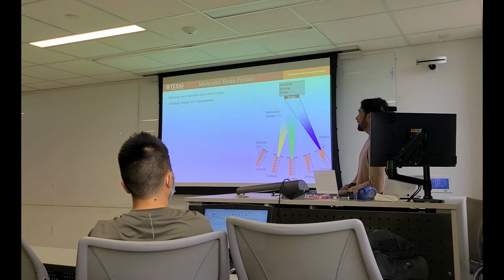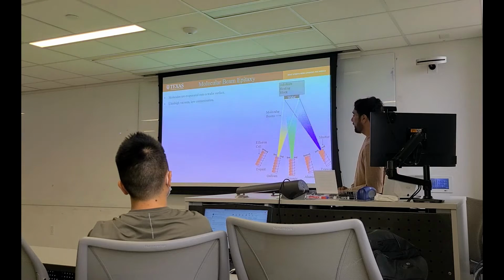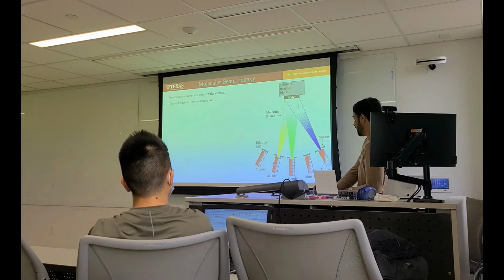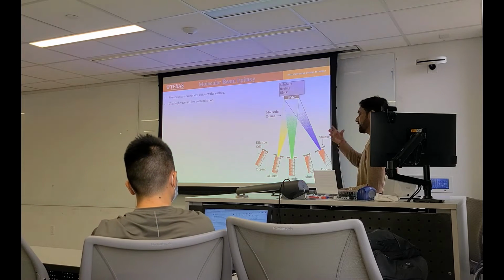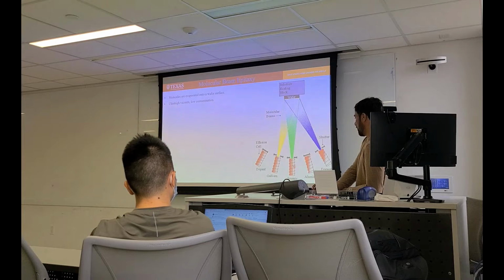The other epitaxial growth technique is MBE, molecular beam epitaxy. They have effusion cells. So these effusion cells, they are kind of crucibles filled with your metal source, and they are wrapped with the heater. As you can see, they are kind of heaters. So we heat them depending on the vapor pressure of your source, and we evaporate them.